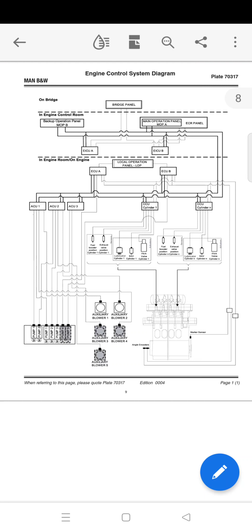Now I will discuss the normal working sequence from this diagram, how it is connected and what all the components are doing exactly in the ME engine. So the EICU, that is the engine interface control unit, receives navigational inputs from the control station and selects the active station based on signals given by the remote control system. The main navigational command is the speed set point, that is the requested speed and direction of the engine rotation.